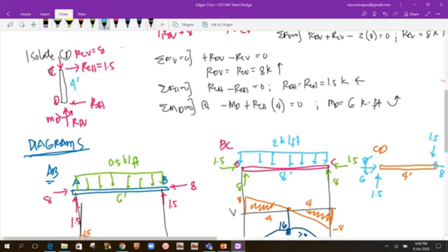Okay, so if we were going to draw the shear, moment diagram and axial diagram of this, ganito lang siya. Starting with the shear diagram. For the shear diagram, you go up with 1.5. Tapos, walang load. So, constant lang yung shear, 1.5. Tapos, bababa tayo na 1.5 din doon. So, di ba, yan yung shear diagram, rectangle.